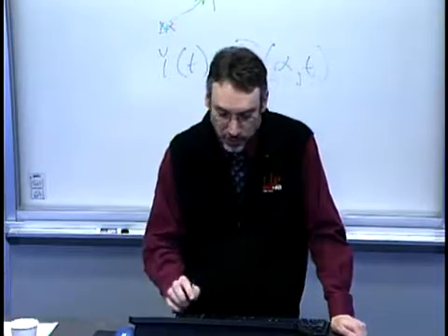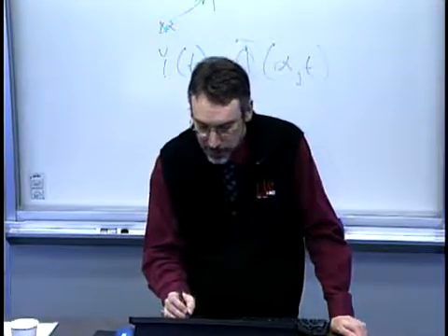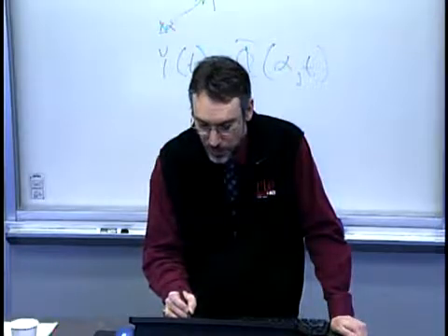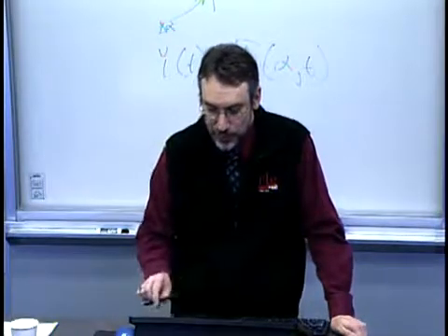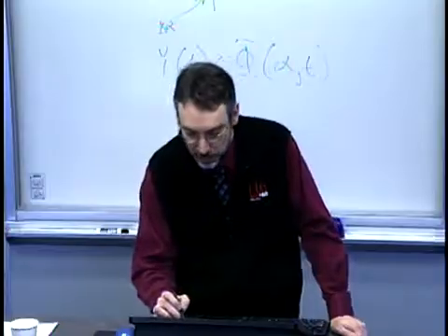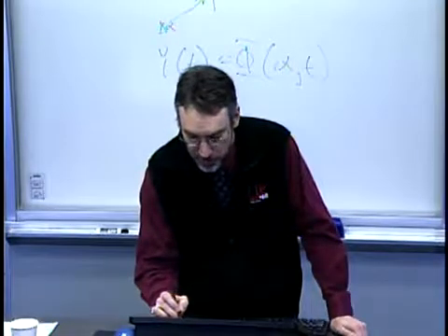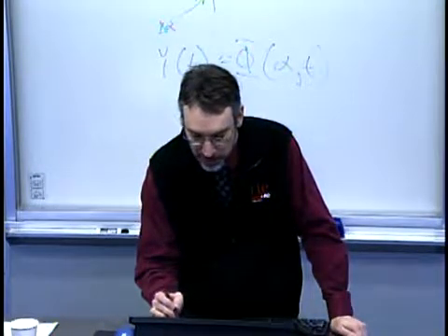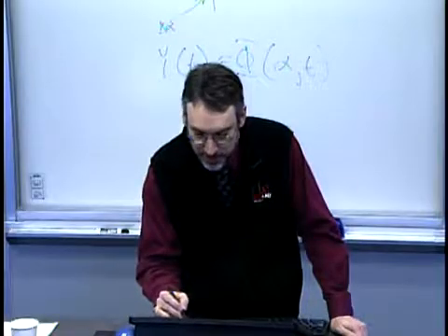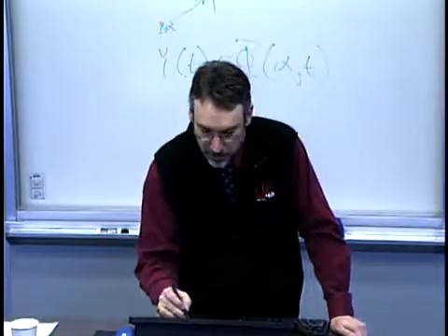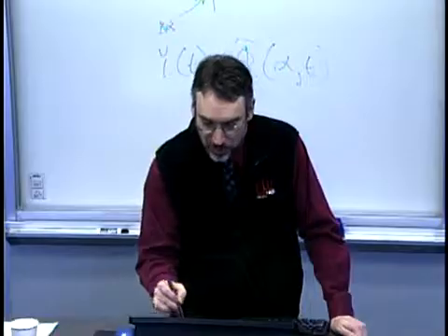But so talk to me about this one. Oh, I guess also here, notice we're plotting two pieces of data. We've got a width and then some average. So it's quite possible that this is a point width at a well-known location, and then the average is we take that measurement on many locations around the part.